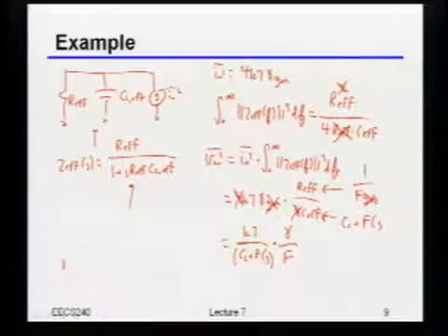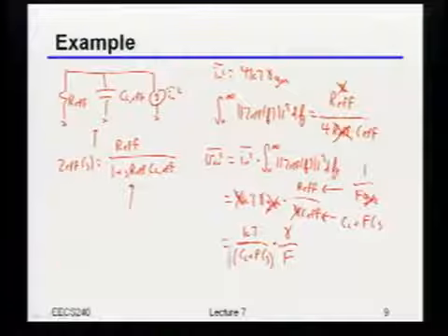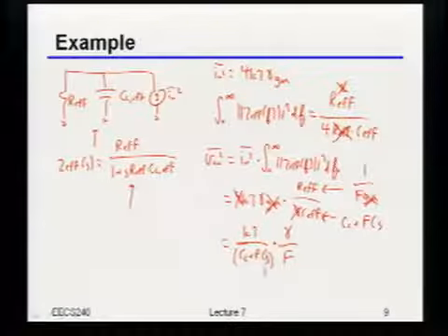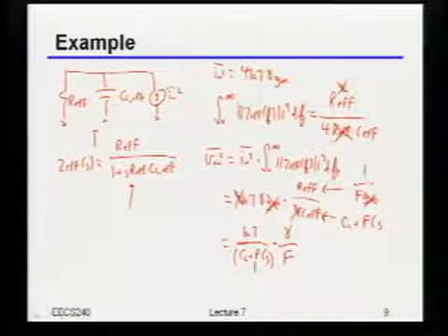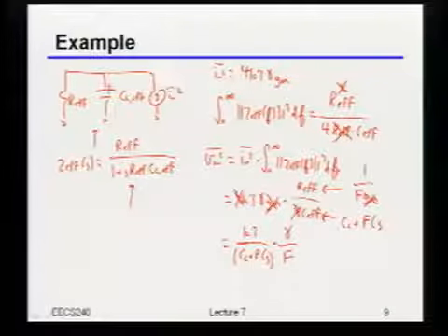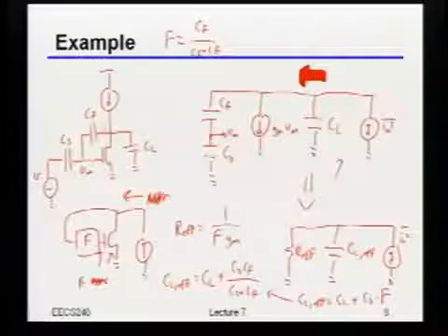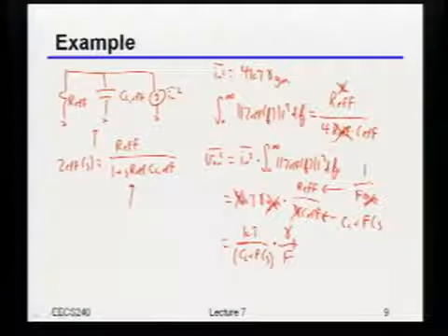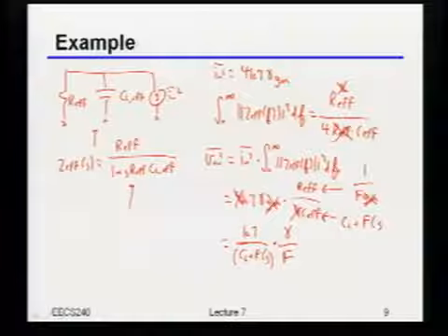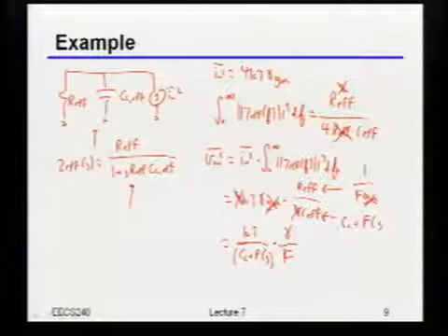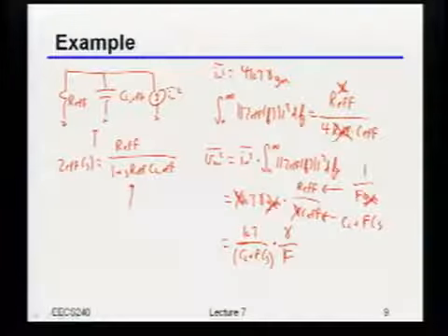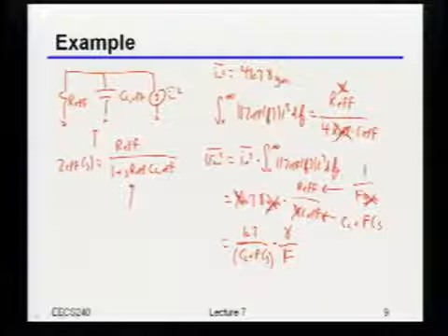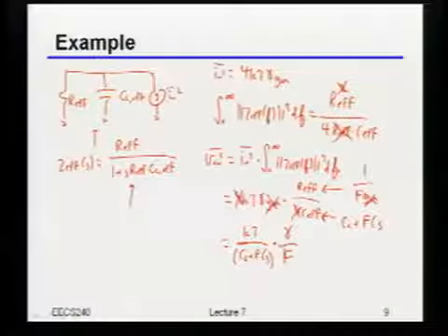Okay, so just like you might have expected, there's some kT over C, and in this case, this C in the bottom is just the total effective capacitance, since we had that capacitive feedback back over here. And then times that gamma, that's just because there's the active amplifier in there, but this 1 over F basically tells you the effective amount of noise amplification you get, okay?